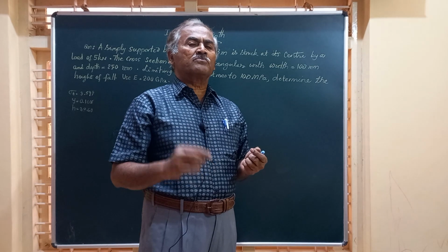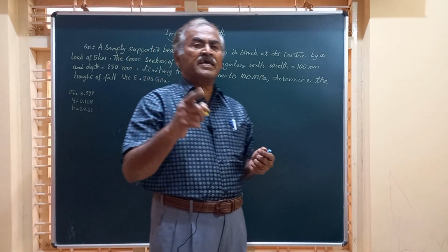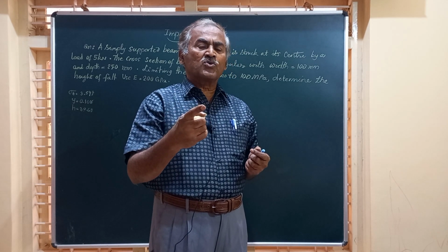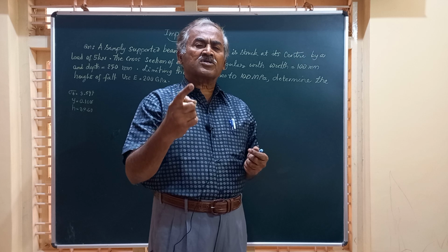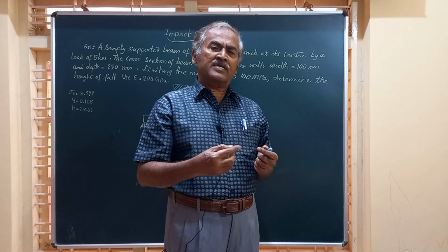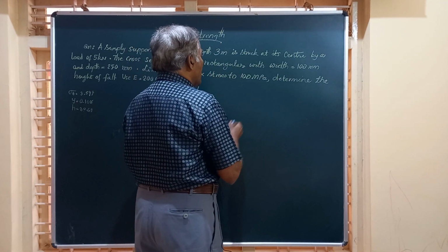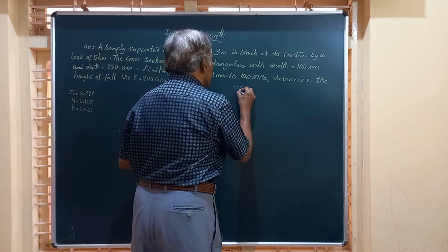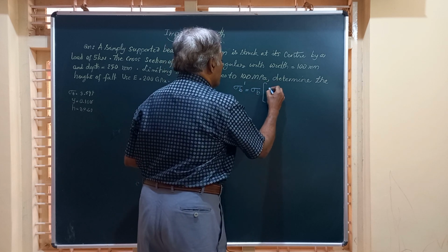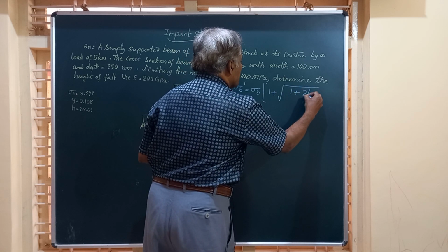If you refer to the machine design data handbook, there is a formula which relates the maximum stress in the member to the stress due to static load and also the height of fall and deflection. For the case of bending, we have the formula sigma b dash is equal to sigma b multiplied by 1 plus square root of 1 plus 2h by y.